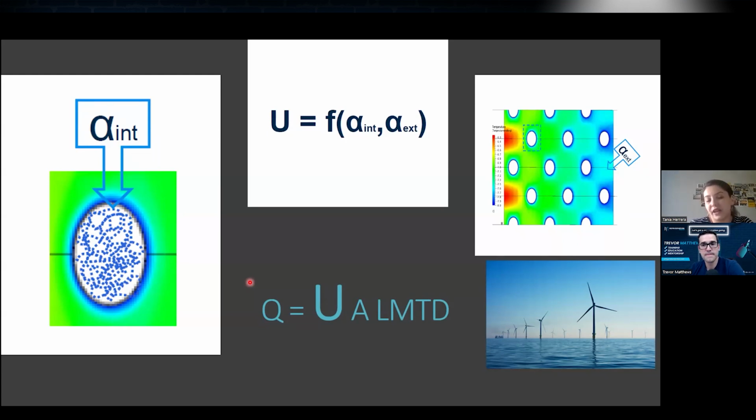As well, it also refers to the second fluid. So in the fin heat exchangers, it refers to the air. So, for instance, well, sorry, I'm going to start again. Yep. So this refers to the heat conductivity of the materials, and this also depends on the needs of your application. For instance, if you have a condenser or a gas cooler that will be installed in a coastal area, we strongly suggest you consider fins with a coating.